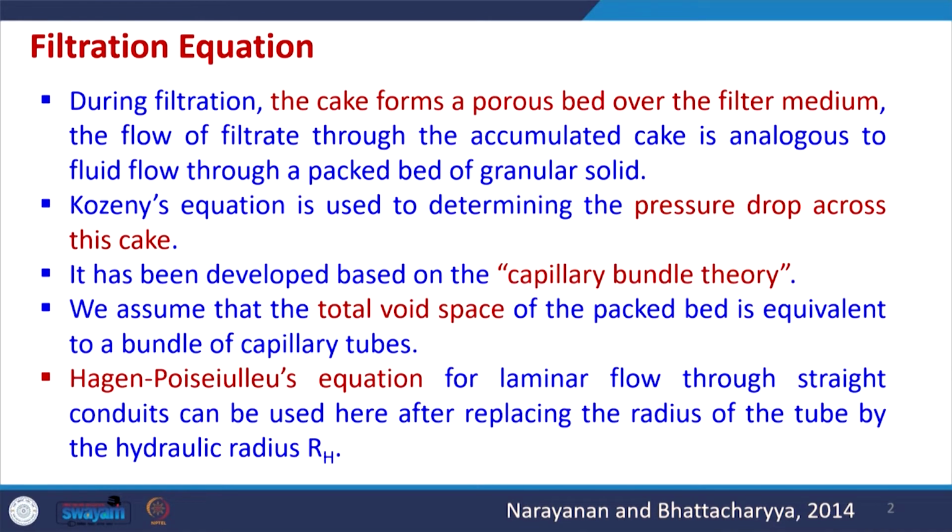Then the Hagen-Poiseuille type equation for laminar flow through straight conduits can be altered by replacing the radius of the tube with the hydraulic radius, and using this we can derive the basic equation and then further modify it as per our necessity.